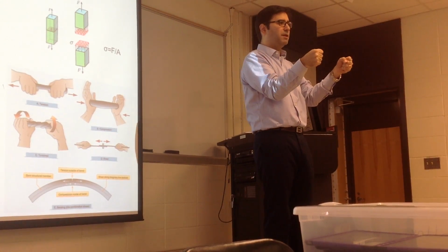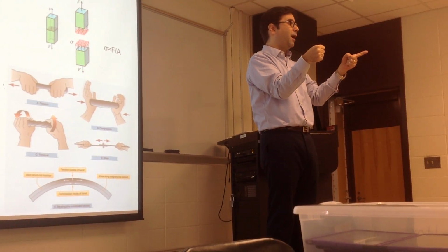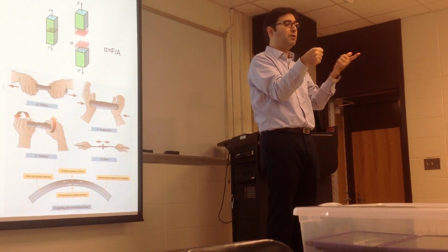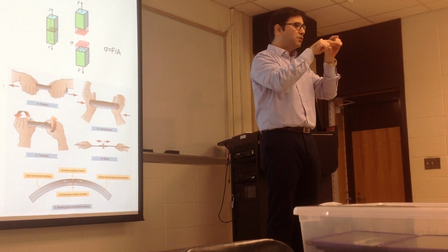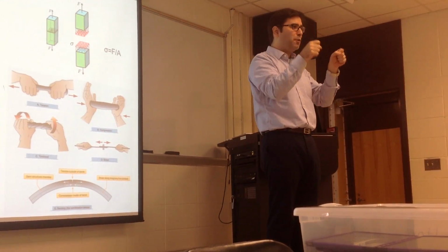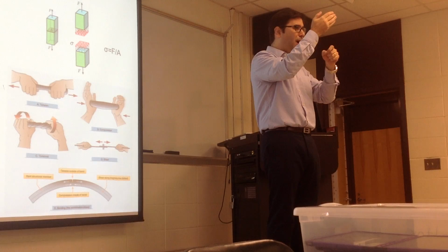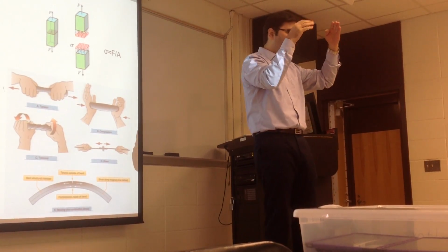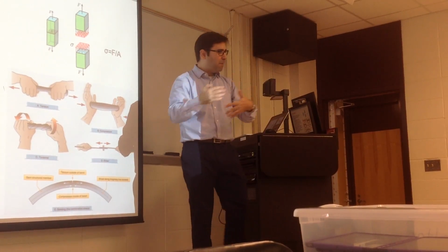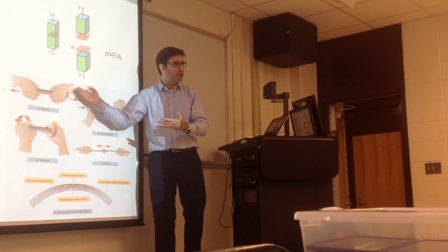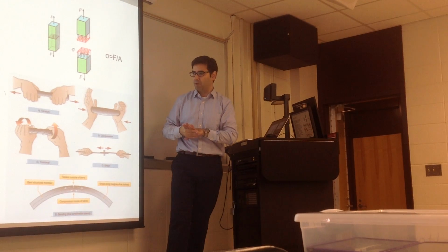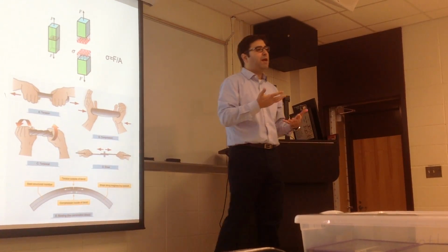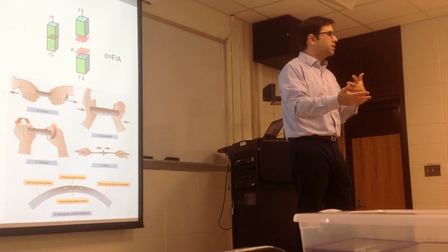And I'm bending the beam like this. Where would you put it? Top. So everyone knows top. Why? Because if you put it in the bottom, it's going to compress your finger. So at the bottom, the beam will be under compression, and at the top, the beam will be under tension. So you can even understand bending in terms of tension and compression, but now it is distributed within the beam.